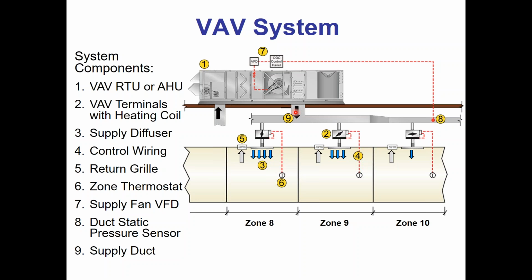If you are a service guy or gal and you go to one of these existing buildings that has a system and you see the VFD is running at 100%, all VFDs in all buildings for pretty much all reasons that are running at 100% are probably not working correctly. Something's broken, something was never configured correctly, or somebody in the building put it in manual mode just to get some airflow going. 100% would be rare.